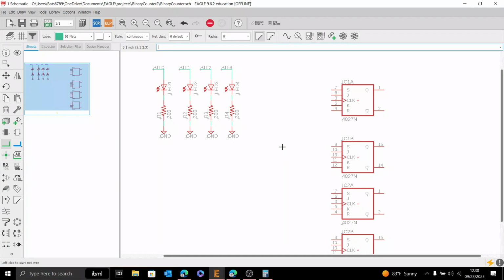So real quick, the idea of a JK flip-flop is that it is a device that can store state. There's a bunch of circuitry magic going on behind the scenes. Your outputs are these Q values over here. If your output is high, Q would be high: 3 volts, 5 volts, whatever you choose for high voltage. And low would be ground. And then Q, you can't see it, but it has a little bar above it. This is the complement output. So if this is high, this is low. If this is low, this is high.